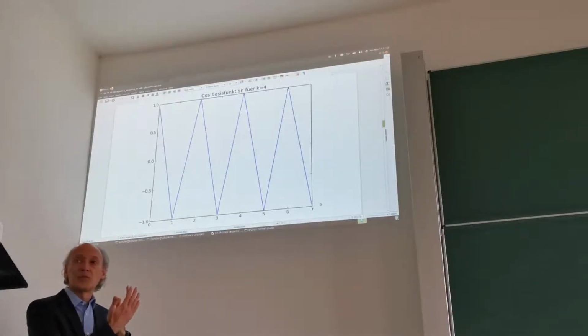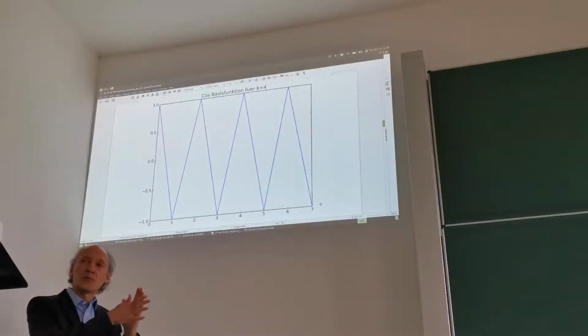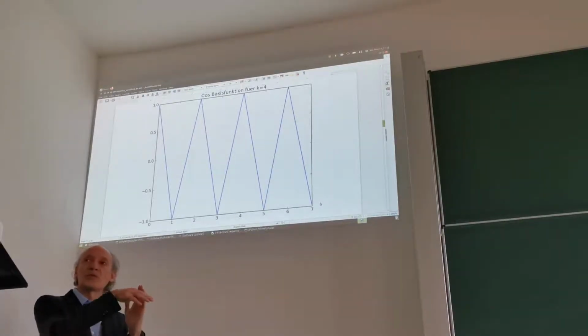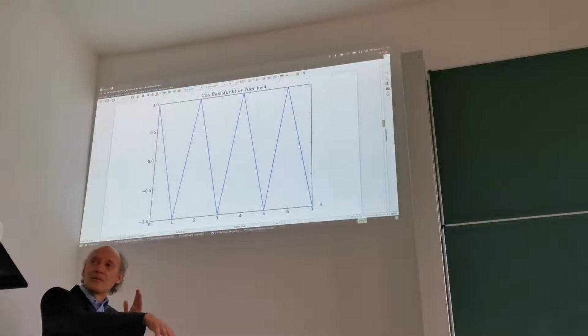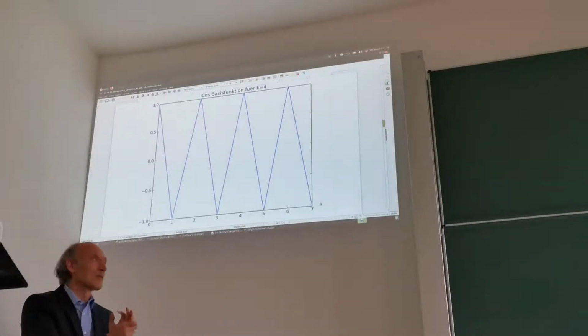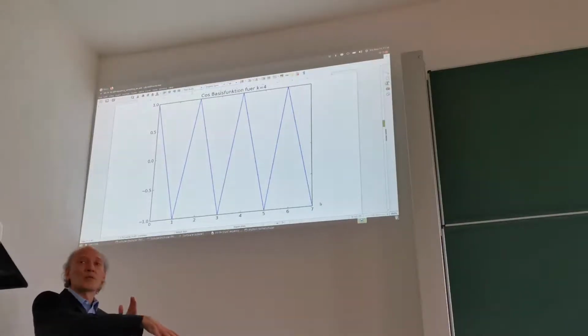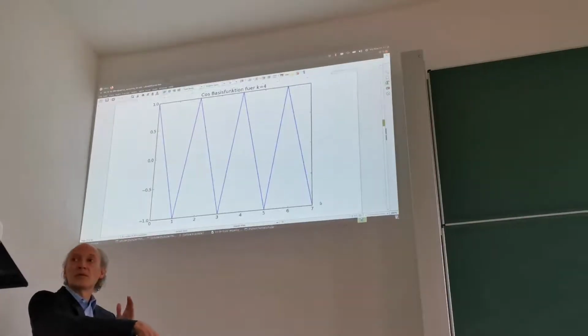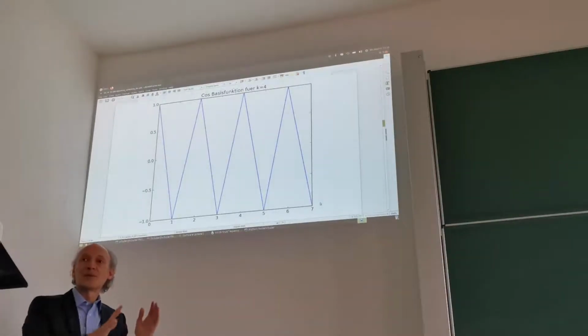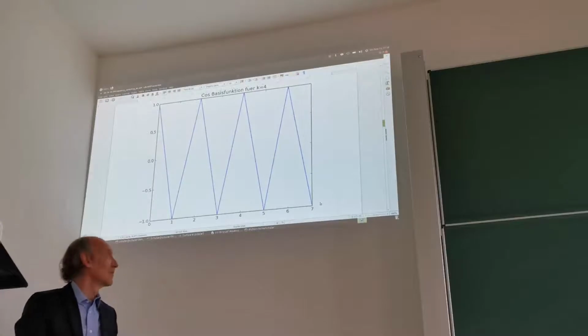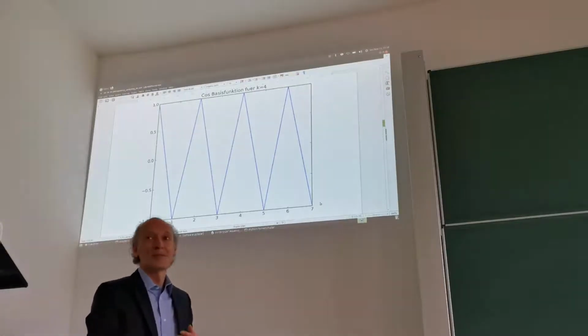So we go up to Nyquist, and then if we increase our frequency, we go down again. And this is this effect, right? If we are going up all the way to n equals 8, we are down at DC again, and go up and down. Make sense?